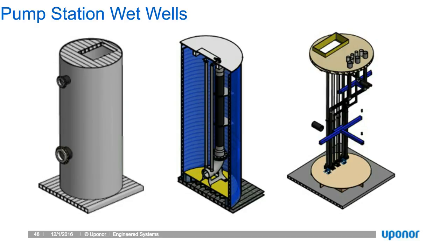And pump station wet wells, we can manufacture up to about 50 foot in depth and 11-foot diameter, complete polyethylene pump station that, again, is immune to hydrogen sulfide, pH, corrosion, deterioration. And we find that this is resonating quite loudly with our public service districts and municipalities who are faced with replacing concrete pump stations and manholes that have deteriorated well in advance of their expected design life. So we can produce pump station wet wells as well.